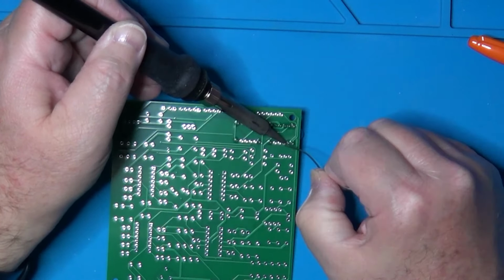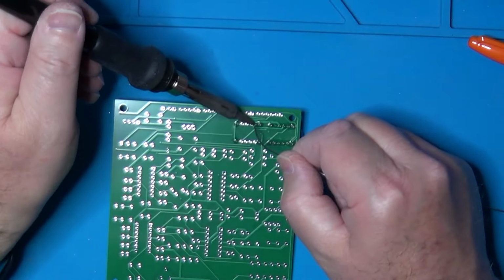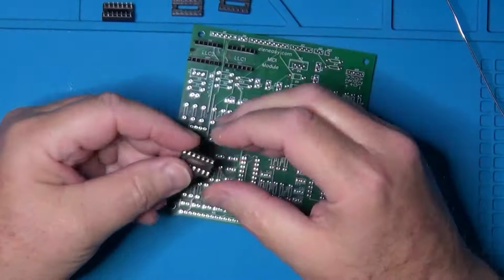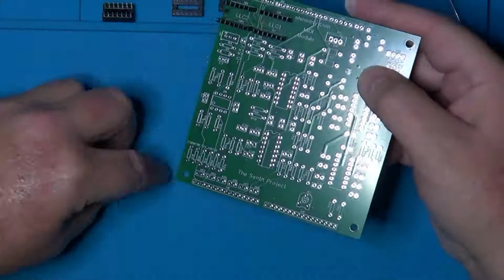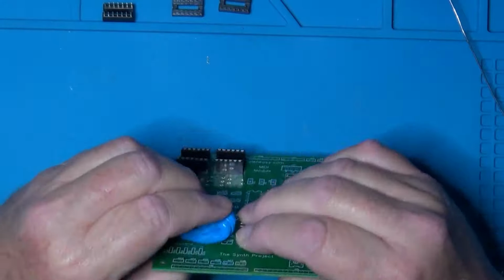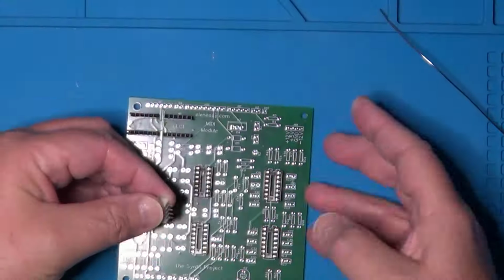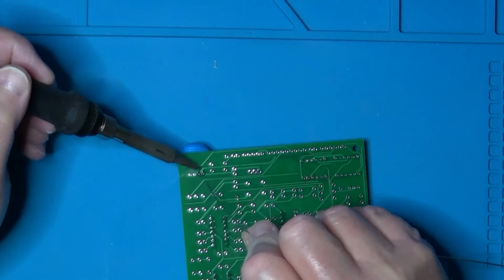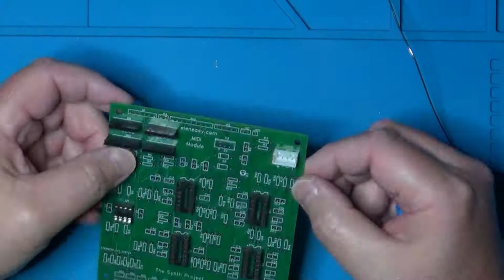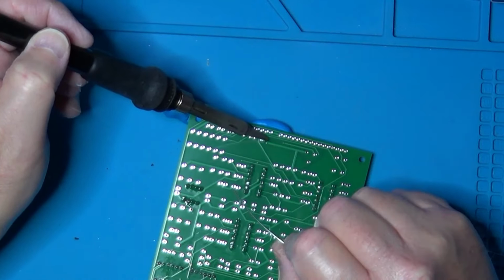I also used the same pin headers needed for the Arduino to create the sockets for two small logic level adapters that bring the Arduino 3.3V output levels to the 5V necessary for the LCD and for the trigger and gate signals. I also used regular IC sockets for all the other ICs on the PCB to make their replacement easier in the remote eventuality that one of them needs to be replaced.